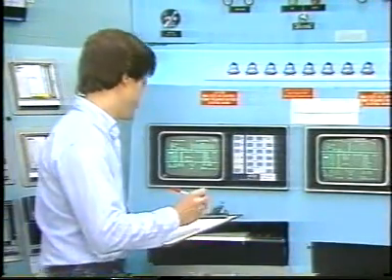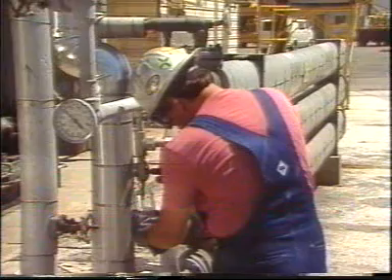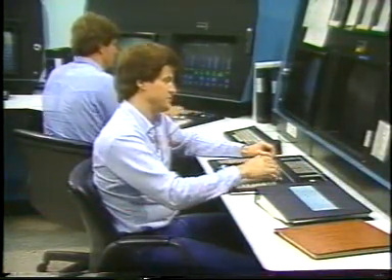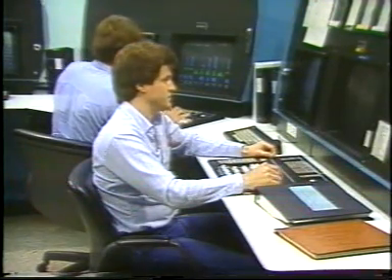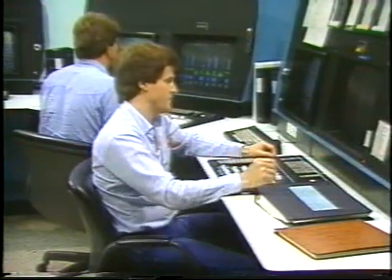The properties of a distillation product are determined by the type of hydrocarbons that are present in it. To ensure that distillation products have the desired properties, certain standards or specifications are set to control their composition. The products are then periodically tested to make sure that they are meeting these specifications. These tests are sometimes run automatically by instrument analyzers. In other instances, an operator collects a sample and sends it to a laboratory for testing. If tests indicate a product is not meeting specifications, operating conditions inside the tower must be adjusted to change the composition of the product and bring it back on specification.